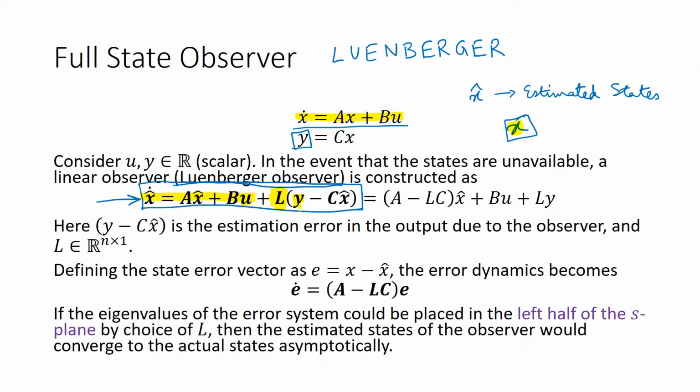However, we would always add something, so this is a simple linear observer. If you look at any advanced observer that you would come across, you would see that this is the philosophy employed everywhere. First we copy the state equation replacing x with x hat, and then we add on some term. Here that term is L times (y minus C x hat).